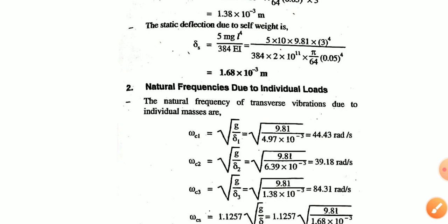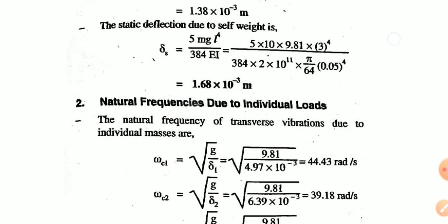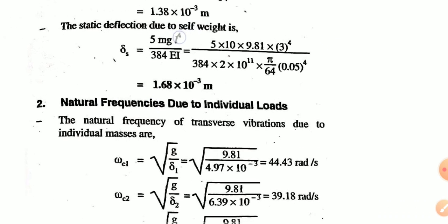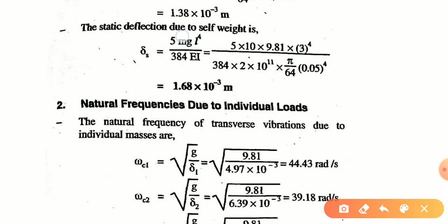So we can find the static deflection due to self weight by this equation, 5 times m g, or we can say w, L raised to 4 upon 384 EI.